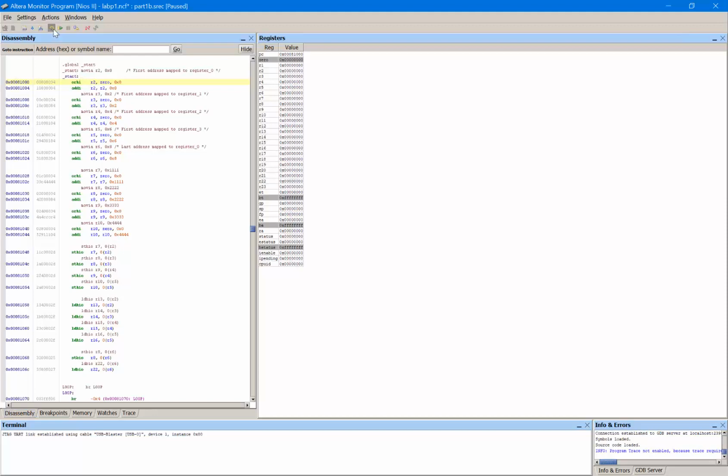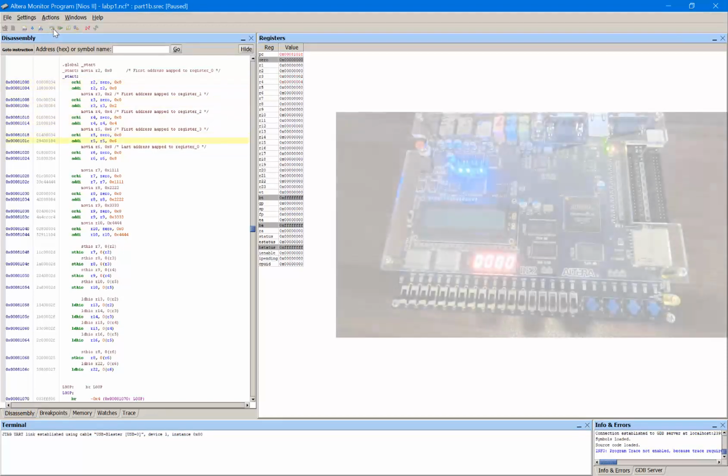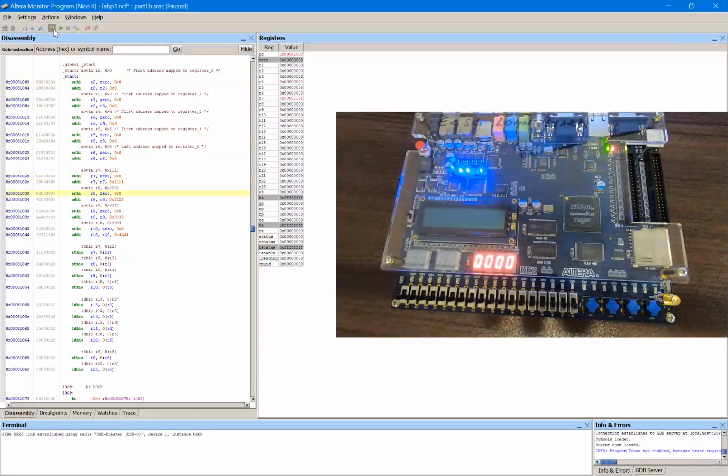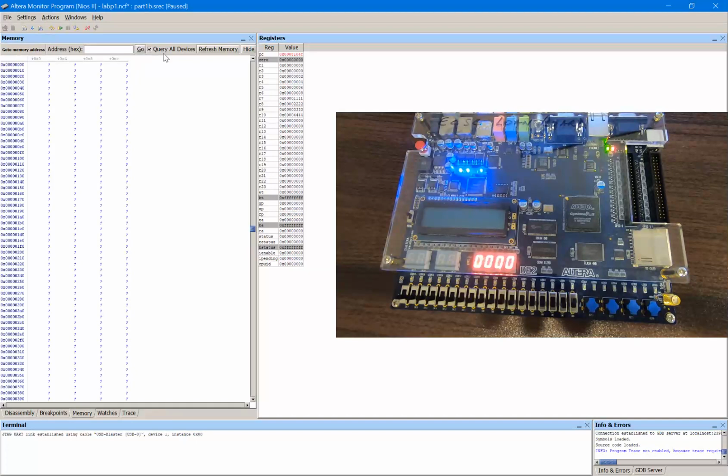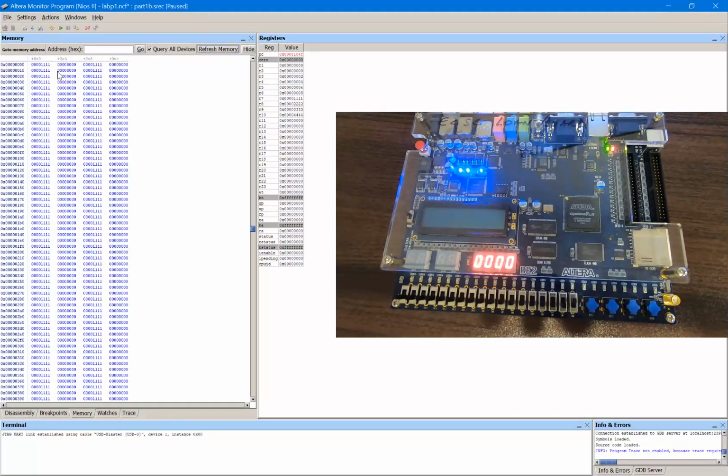Okay, and then we will step through. So we're storing 2, 4, 6, 8 for the addresses, 1s, 2s, 3s, and 4s. Now the first store half word should make register 0 all 1s. Yep, which it has done here. The next store half word should make register 1. Before we do that next store half word, let's go to the memory and check what that first store did.